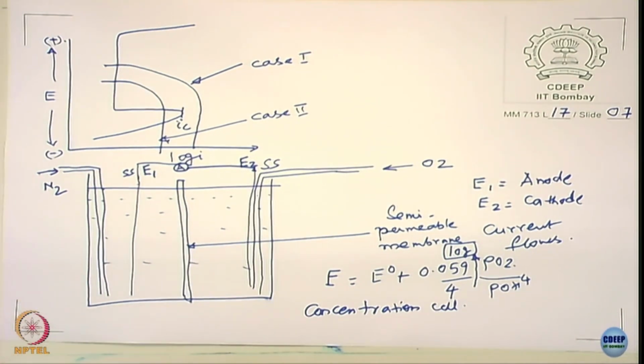That leads to corrosion of metals. Now, this is only one reason for crevice corrosion, only one reason for gasket corrosion, but you will see that that is not the only reason for that. Okay, you will see the environment plays a very important role. We'll talk about it soon, but the major initiative comes from the concentration cell, because the concentration cells make one place an anode, then another place a cathode, making localized anodes and localized cathodes at macroscopic level.